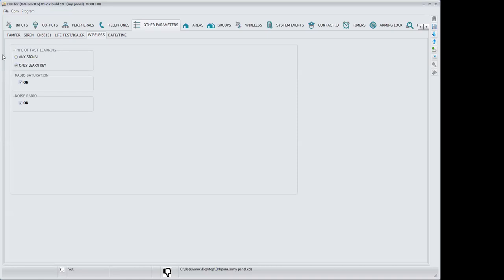In this way, it's possible, for example, to put all the sensors on the table, put in all the batteries, and be sure the enroll does not start. Understand what I mean? You have all sensors on your table, powered, but the system does not start to enroll. When you push the red button, the system starts to enroll. In this way, you can set one specific order to enroll the devices. In the other case, when you put in the battery, the system starts to enroll, because it is an automatic signal from the device. Normally, it's better to use the specific button for enroll. This parameter is that.